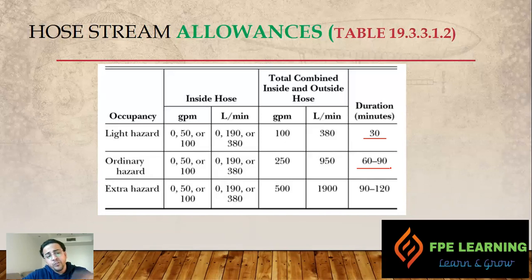And suppose you don't have any inside hose, in that case also we have to use the outside hose requirement, right? We have to use the outside hose requirement in the system, and that is mostly for the fire department team. They will come and they will extinguish the fire, right? Mostly speaking, the outside hose allowances typically receive their pressure from department apparatus, right? And similarly for the inside hose, right?